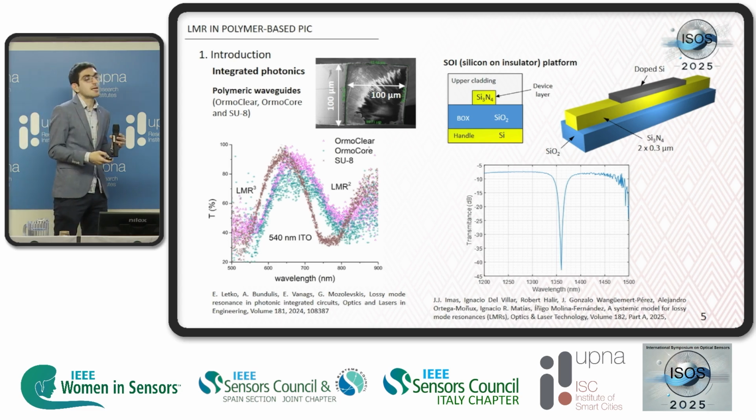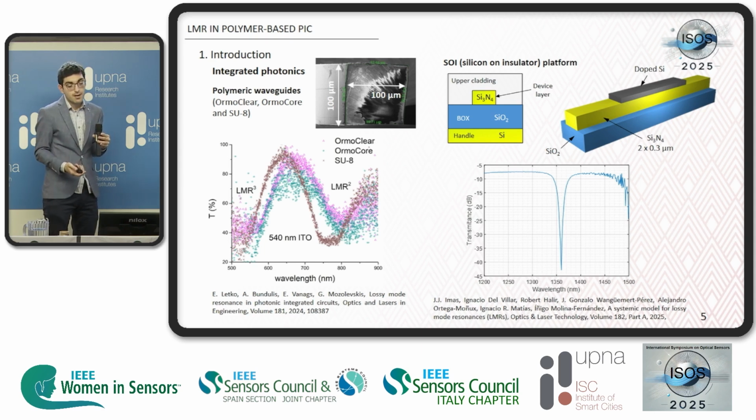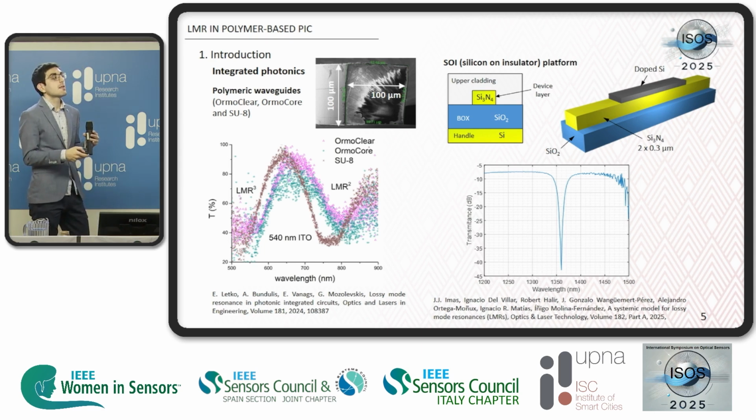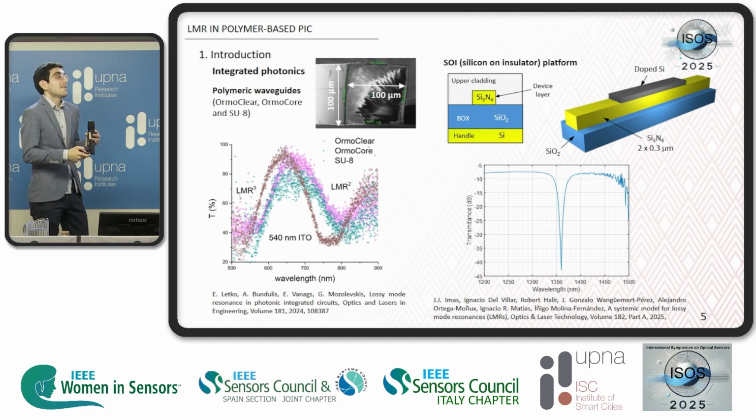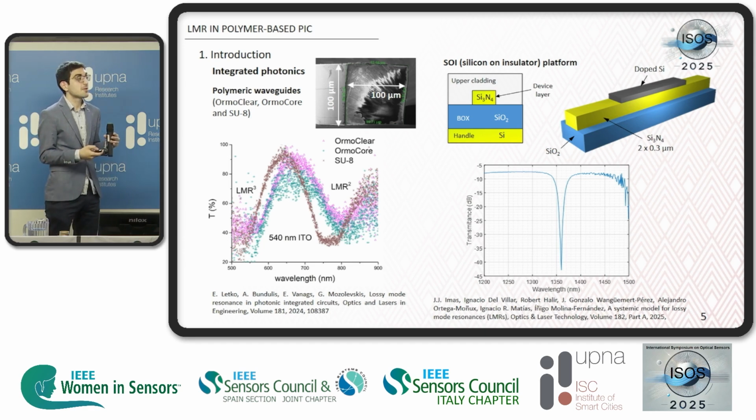What's the problem of this? Even if the resonance seems better, the problem is that this is difficult to manufacture. The silicon nitride photonic wire is pretty standard, but the problem is how you do this. You need to perform the deposition of a silicon thin film only on part of the photonic wire, and what's more, it has to be doped, which is very ad hoc, and it starts to be really expensive. So this gives good results, but it's not a practical implementation.